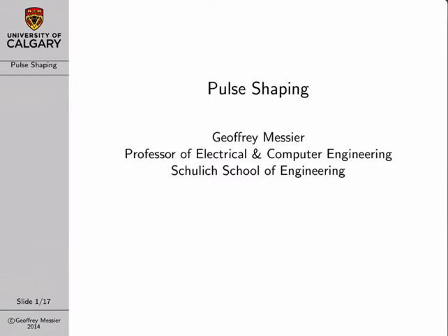This is important because in earlier modules, when we introduced things like modulation, we tend to use simple pulse shapes like a square pulse or a triangle pulse, where the entire energy of the pulse is completely confined to within the symbol time from 0 to T. However, most actual communication systems don't use these kinds of pulses.